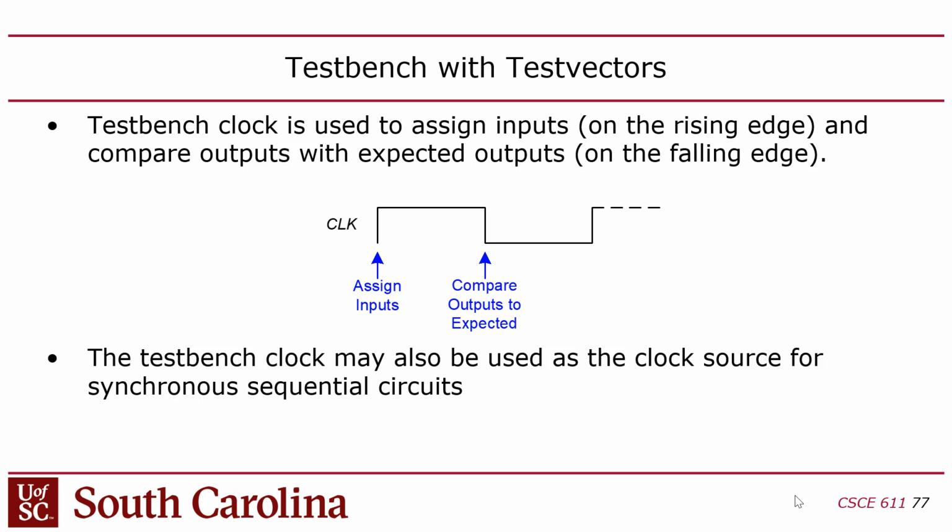okay, let me clarify. So this is a combinational circuit, and I'm going to use a clock, even though clock is not part of combinational logic, but I'm going to use it just to run the test bench, right? If you have sequential logic as your design and your test, then obviously the clock matters, and you may have to write a test bench that, for example, waits for 5 clock cycles after the inputs, if that's the delay of that logic operation. Like if it's a 5-cycle operation, you may have to count cycles.